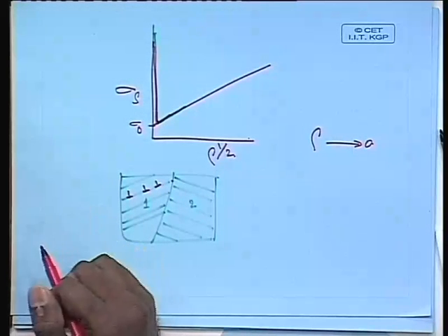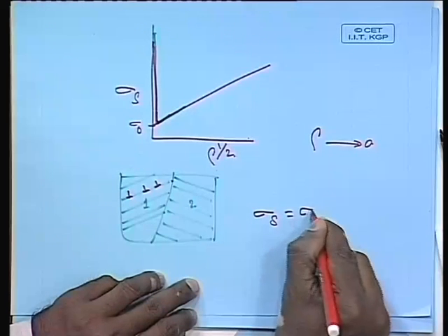So, it has to stop, and then you have to put in more stress so that you can induce dislocation movement on the other plane, on the same type of 111 plane in the other grain. So, as a result the stress required will be higher, and this increases if you increase the number of such boundaries. So, what is the way to increase the number of such boundaries? By making the grains finer. If we can make the grains finer, we can have much more obstacles for the dislocation movement, and this is usually given by an expression like this.